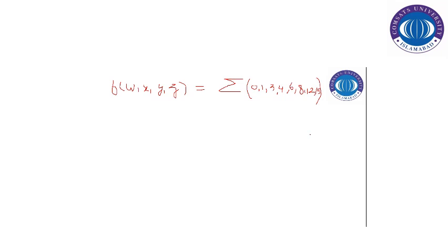So we have to implement that, and we will see how we implement it by using the primary gates, as well as by using the techniques that are used to simplify the Boolean function, and then we will see how to implement that function by decoders only, then with multiplexers, and then tristate gates. The first step for the student is to make a truth table in order to see the relationship. But if you know the terms and it's a four literal function, we can directly write those terms and convert them into the Boolean function in the form of literals.